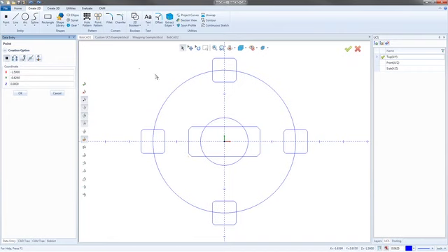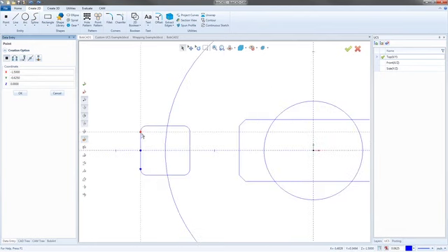Right here, if I come in, I can drag this point around with me and place it on things, or I can go in and type exactly where I want to put this point. One thing I can also do is use this to snap it onto specific areas, and I'll talk about the snapping again in a second. If I want to snap a point onto this snap point, remember anything you were doing in the past with any sort of snapping was always jumping to a snap point. It has to snap to a snap point.